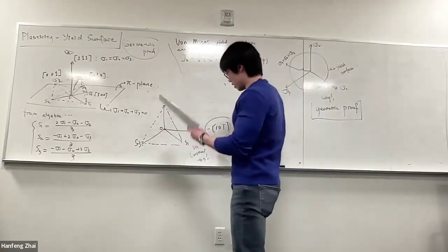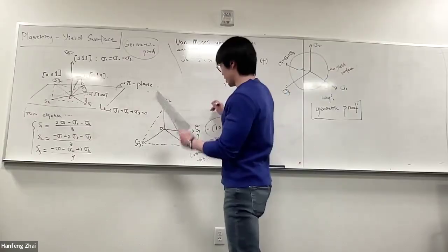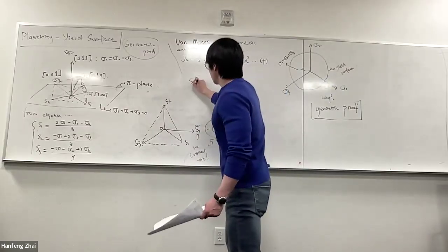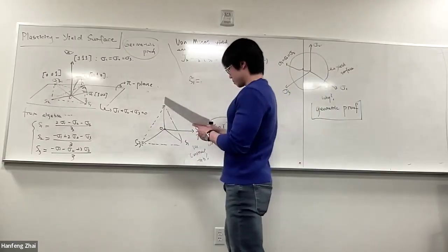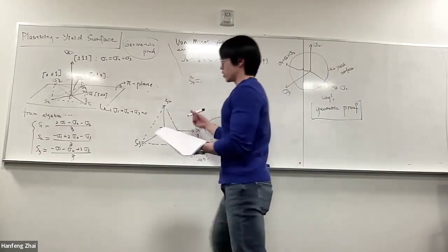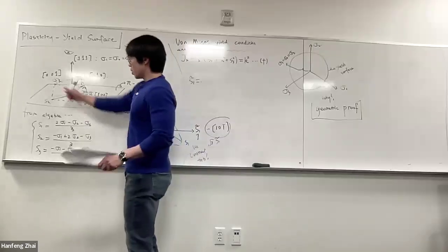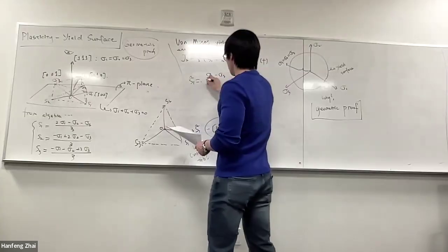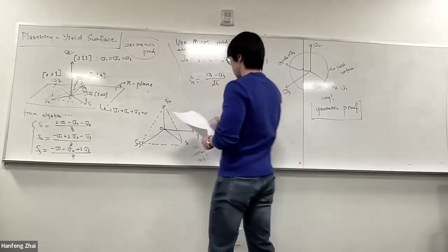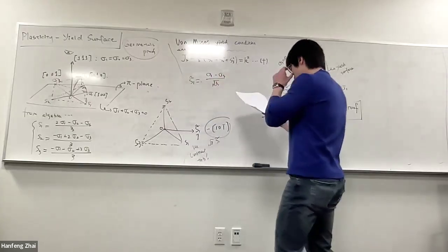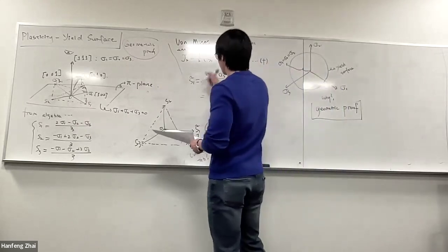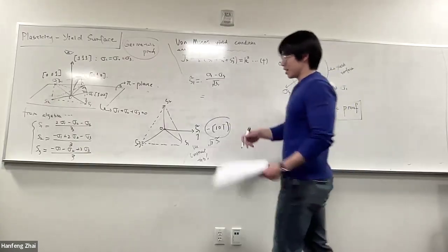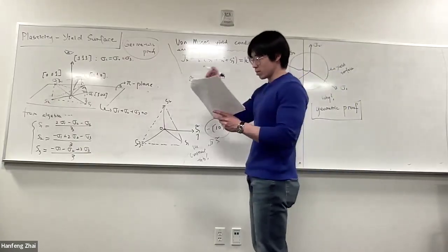So what is S1 tilde mathematically? How do we write that? S1 tilde can be written as a function of sigma 1 and sigma 3. So it's actually sigma 1 minus sigma 3 divided by square root 3, which you substitute the equation I just wiped out, you substitute the hydrostatic, and the hydrostatic stress can be canceled out.